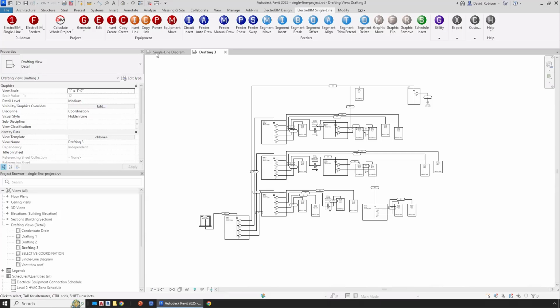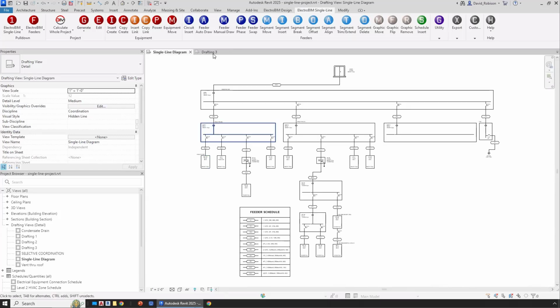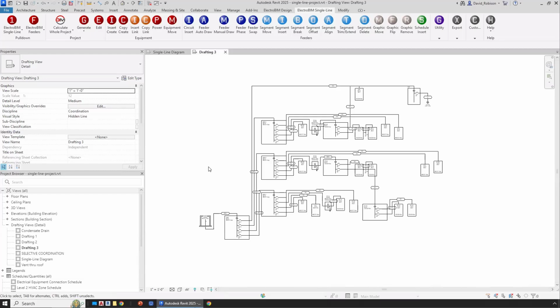And in both cases, the single line diagram that we used to have and in the new riser, the idea is that we do a drafting that's pretty good. It's going to get you 80% of the way. But from here, you're going to want to do adjustments on your own to get this drafted how you'd actually like it to look. We do pretty good, but it's never going to be perfect. And there's always going to be a little place for you to come back and just adjust what this looks like so that it's clean and having the information that you want.